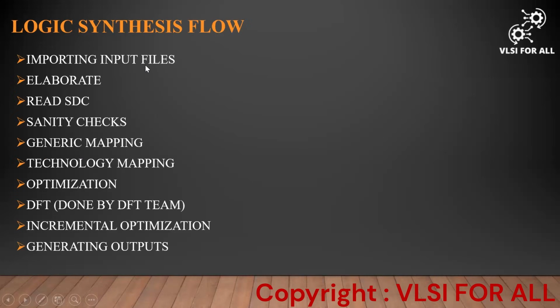In the first stage, it is importing input files. The second stage is elaboration, read SDC. The third stage is sanity checks. And the fourth one is generic mapping, technology mapping, optimization, DFT, incremental optimization, and generating outputs. So these are the stages which come under the logic synthesis flow. We'll discuss each stage one by one.